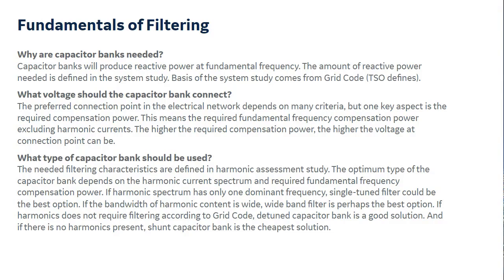And then again, if you don't have the harmonics, then a shunt capacitor is always the cheapest solution. But then you will have some issues. You can have resonances, and you can have all sorts of issues. We will get back to those also later on.